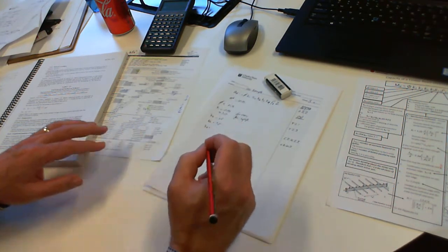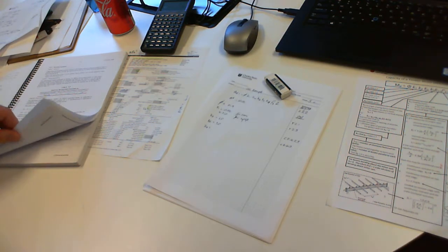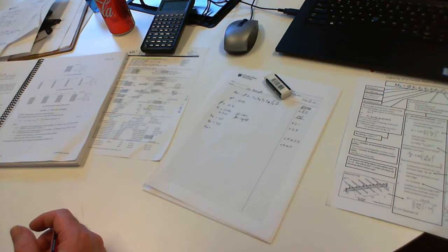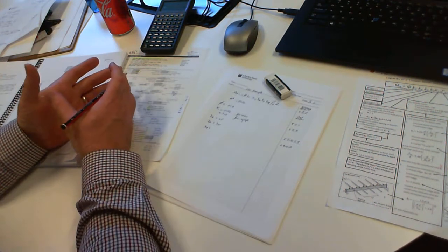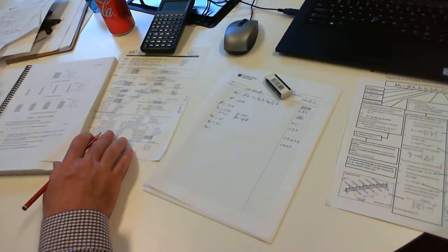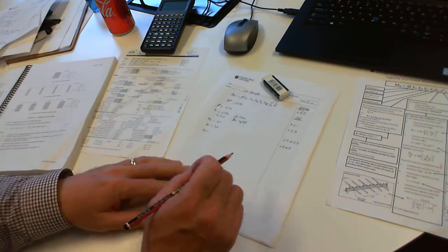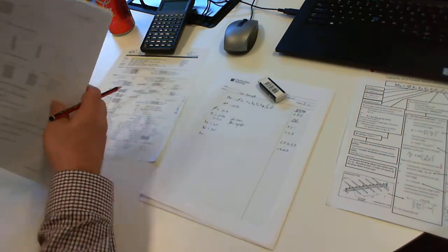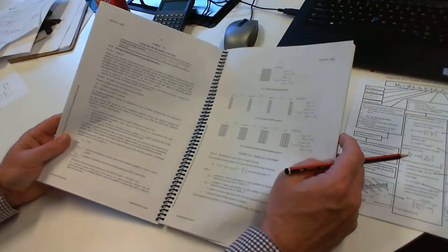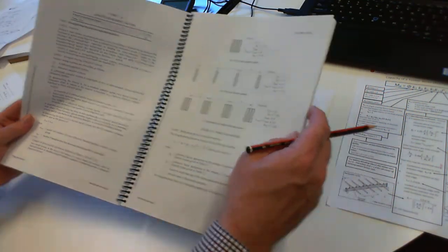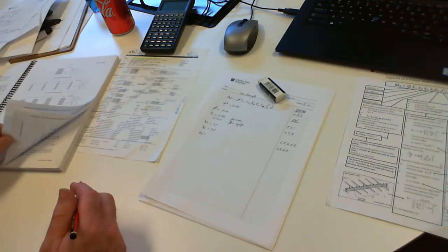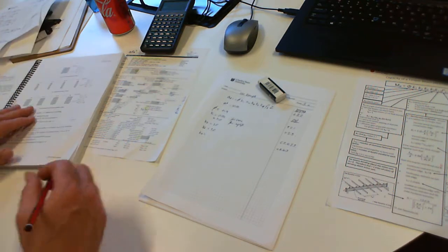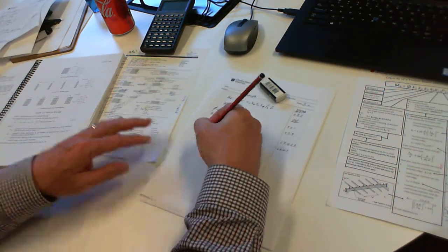Alright, K9 factor is a strength sharing factor. Basically, is this beam on its own, or can it share strength with others? And to do the K9 factor, you look at the section here in clause 2.4.5, and to get to the K9, you need a thing called NCOM and NMEM.